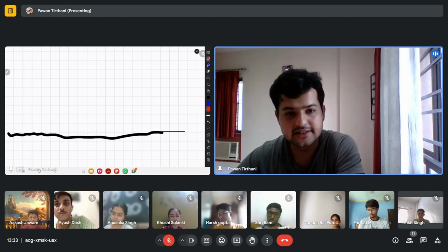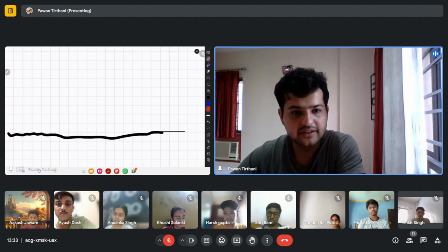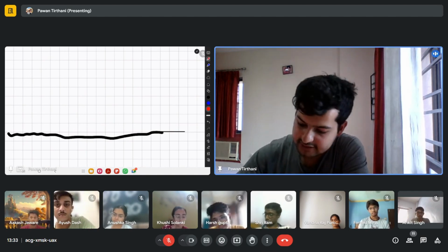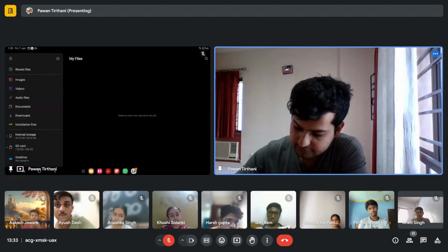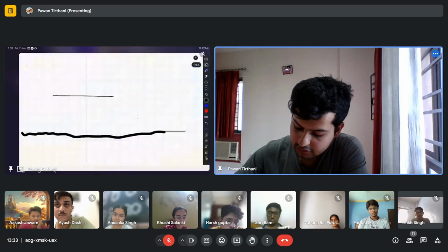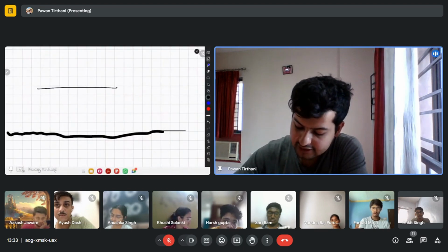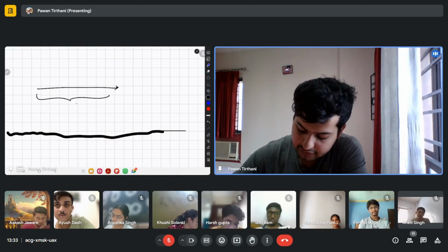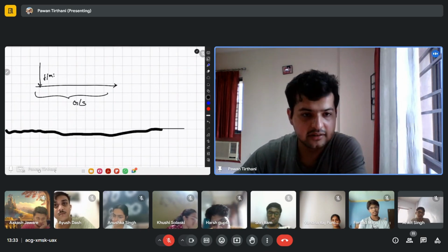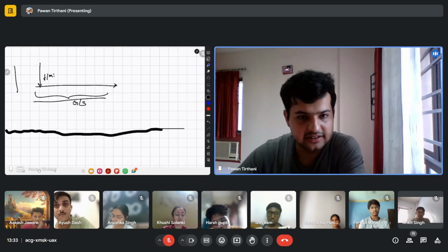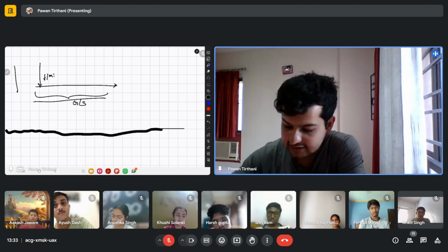आप लोगों ने 1 and 60 रूल किया हुआ है. आपने 1 and 60 रूल में ये किया होगा to maintain a 3-degree glide slope. To maintain a 3-degree glide slope with X amount of ground speed, you need a certain rate of descent, right? For a certain ground speed, you need a certain rate of descent. We have all done this. कैसे निकालते हैं हम लोग?